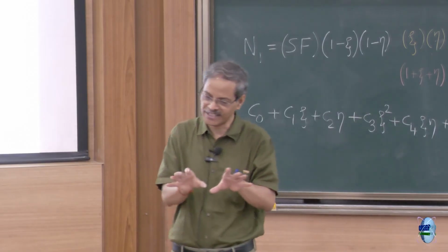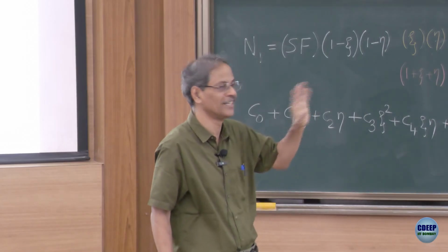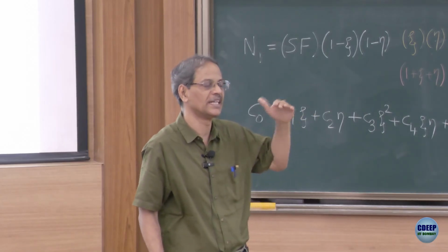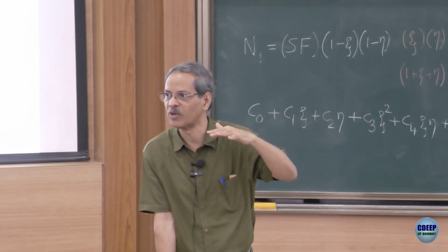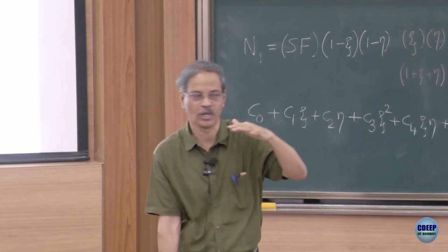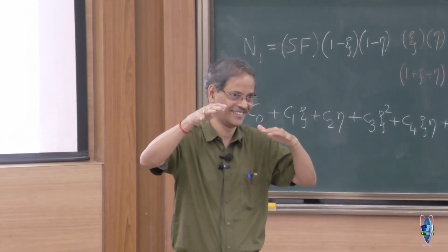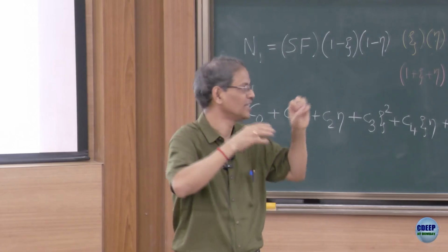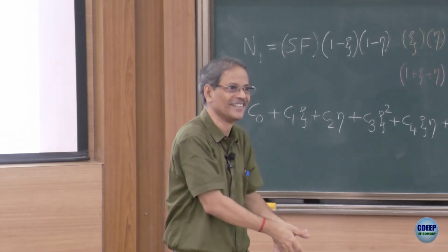It is not necessary that all the additional terms have come, then you would have got zeta cube and eta cube also. But you can guess now, if I were to think in terms of a cubic shape function to approximate the curved element geometry even better, then I would have zeta cube, eta cube, but then this diamond will go even deeper down.